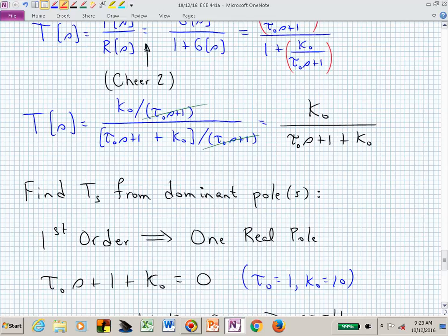What do angles give us in terms of transient behavior? Design specification. The angle theta is related to zeta, and zeta is that figure 5.7. When I start saying this, you need to be visualizing not just tubes, but zetas and thetas. And what's zeta associated with from figure 5.7? Percent overshoot. So you shouldn't be expecting a percent overshoot, should you? If this is a first order system, if this is an RC circuit, how does your response behave?